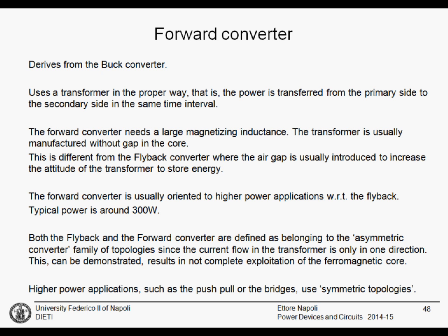This is different from the flyback converter, in which the primary winding was storing energy during the on phase of the switch, and during the off phase of the switch, this energy was forwarded to the output. In this case, we have a continuous flow of energy when the switch is on.